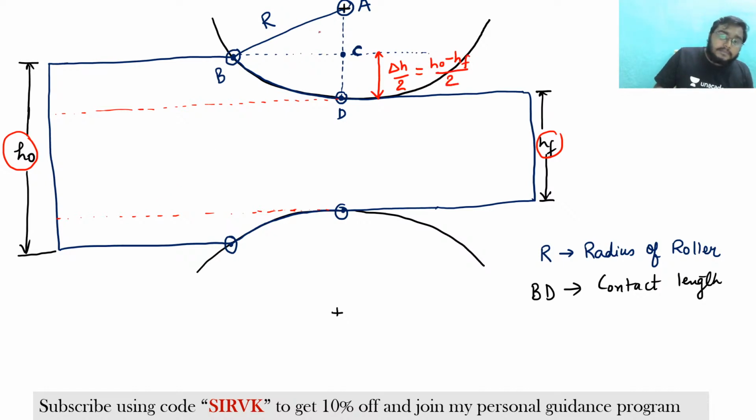Now this roller is making some angle. Suppose this is the B and this is the D. Contact length is there. So from this contact point of the workpiece and the roller, the angle is being made. That angle alpha is known as the angle of bite. Okay. Now understand this concept.